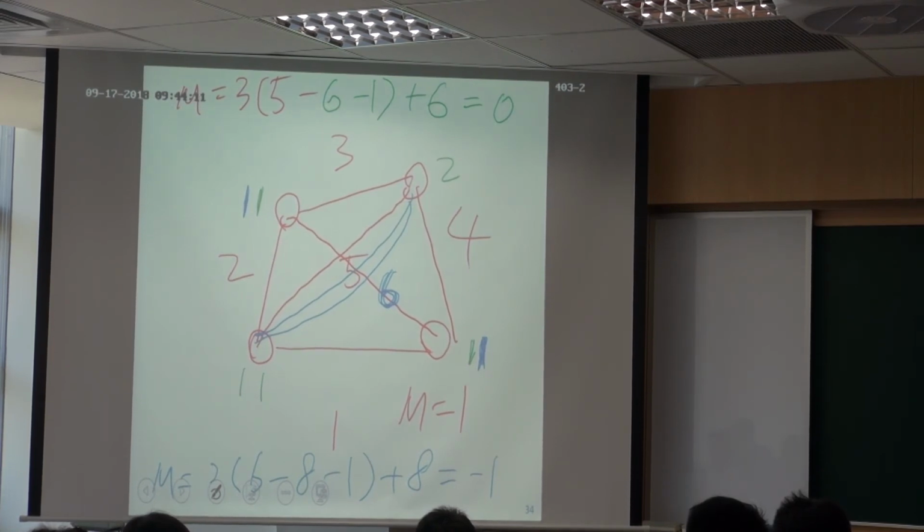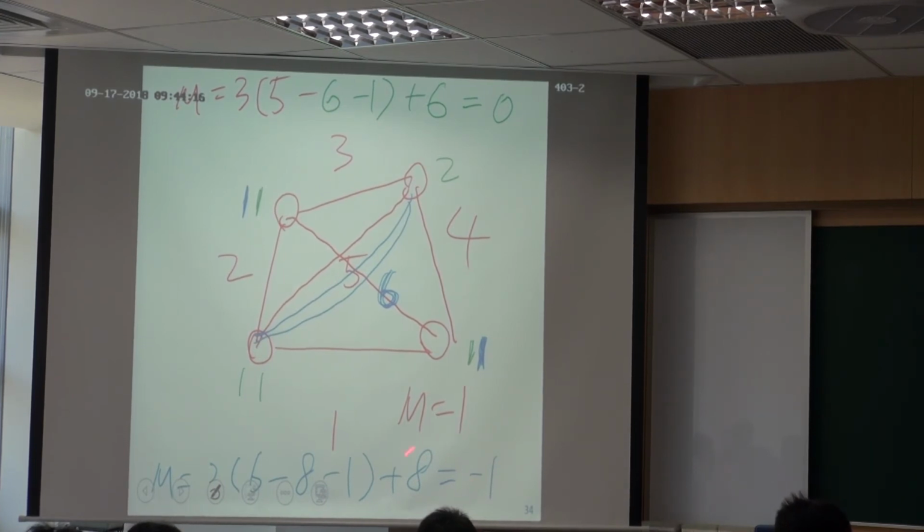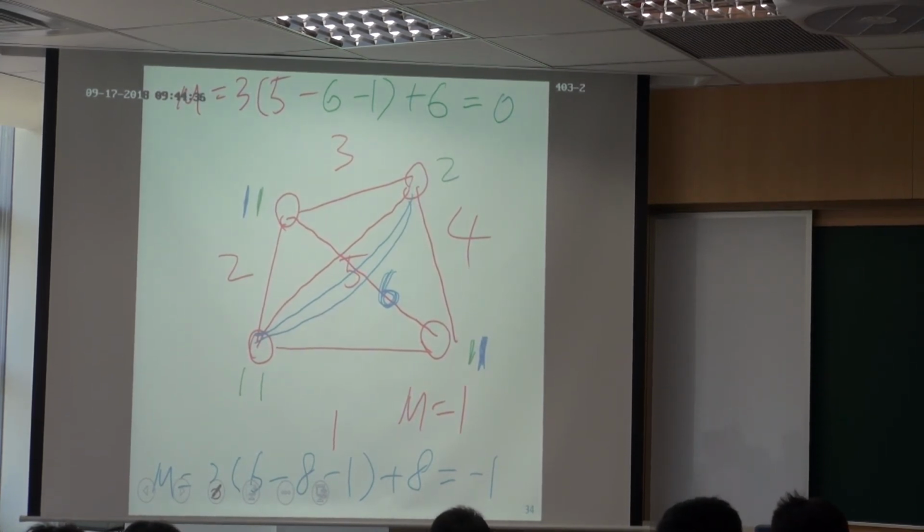So we call this case over constraint, because we add too many links, and by calculation, every link you add into this mechanism, you will add some more joints, but these joints will actually add more constraint in the equation. So that will result in some error answer, some wrong answer. Any question about this one?